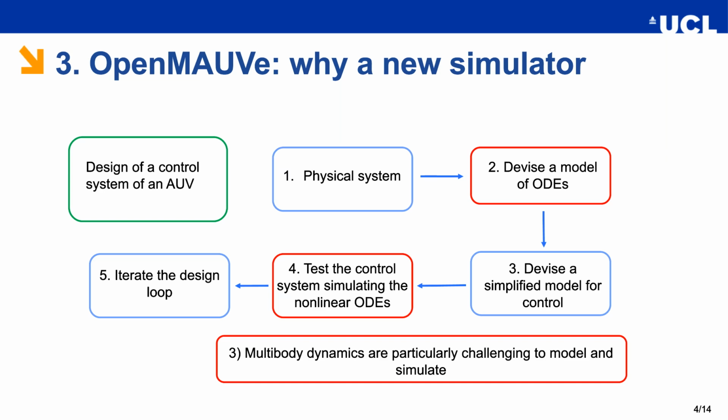Third, when we are talking about multi-body dynamics, which are the most appropriate modeling paradigm to describe underwater gliders and hybrid underwater vehicles, the dynamics are even more convoluted to simulate, as they might give rise to systems of differential algebraic equations which cannot be handled easily by standard solvers. This comes from the fact that the reaction forces exchanged between the internal moving actuators and the vehicle hull do give rise to algebraic constraints, which might translate into algebraic loops which require handling by expert users.